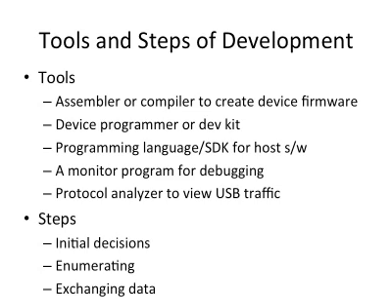You probably need a device programmer or development kit. PIC18 is an example. You need to have a programming language and SDK for host side software development. You need to have a monitor program for debugging, and most importantly, it will be very helpful if you have a protocol analyzer to view the USB traffic over the USB bus.